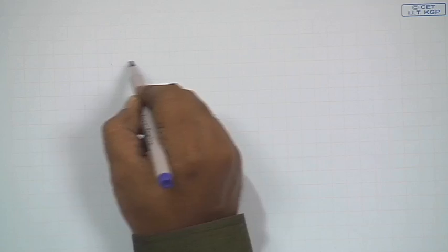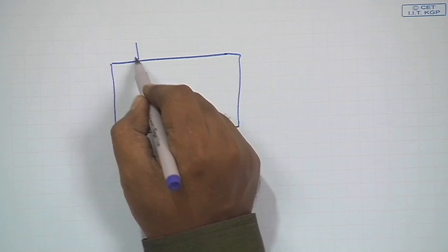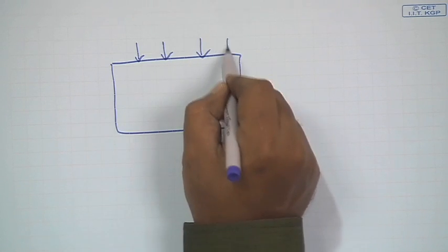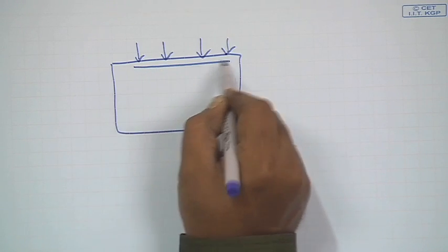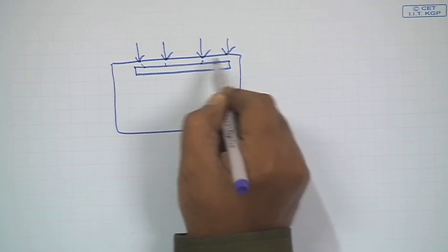So, that is why the storage elements of the control path may be replaced by scan cells, whereas storage elements in the data path are not put on a scan cell, because we do not want to put some values, because ultimately the values will be coming from the system primary inputs. In fact, any digital design, if you look into it, is like this. If this is the system boundary, we have the inputs coming from the outside world, and at the first stage there will be registers which will be holding these values.